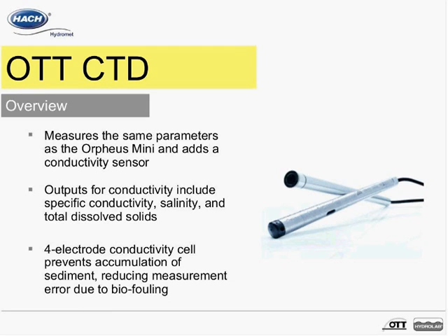The conductivity sensor's open cell design further reduces measurement error as sediment falls to the bottom of the cell while bubbles rise to the top. The sensor is easily cleaned with either a Q-tip or cotton swab.